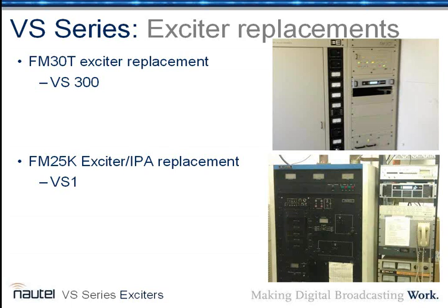So the VS series has a ramp-up time from the time you press RF on to the time it actually makes power. So we had to do a little bit of midnight engineering on how that actually works. When you press filament on, it turns on the VS1 at its lowest power setting, which I believe is 32 watts. And as Jeff is famous for telling me, it'll run into a coat hanger at 32 watts.